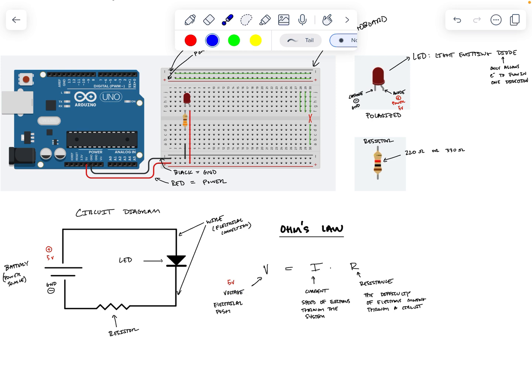Now, when we did that, the light lit up. If you swapped out that 220 ohm resistor for a larger resistor, this R value increased, it went up, but the voltage stayed constant. So as the resistance got bigger and bigger, the current got smaller and smaller, and the light became more and more dim. Now, if you took this resistor and you made it smaller, now the current through the light increased and the light got brighter and brighter up to a point at which it exploded.